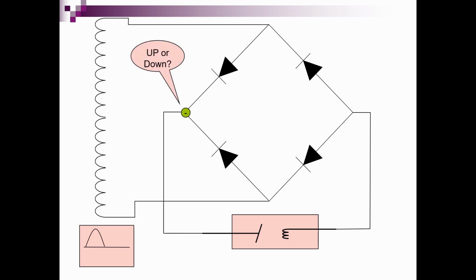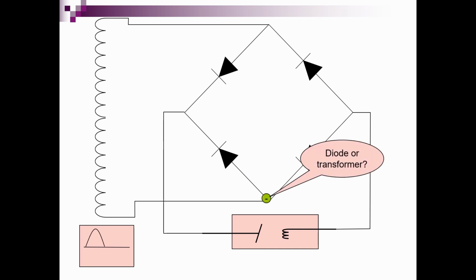The flow of electrons is again at a crossroad, and both diodes are conducting. The electron flow will move to the lower diode, because if they went up, they would be moving towards a portion of circuit that already has electrons, and like charges repel. Finally, the electrons will flow back to the lower leg of the transformer, because if they flowed back to the diode, they would be moving towards the portion of the circuit that currently contains electrons. At this point, we will mark the end of the first phase of the AC wave, and the direction of current flow will now reverse.